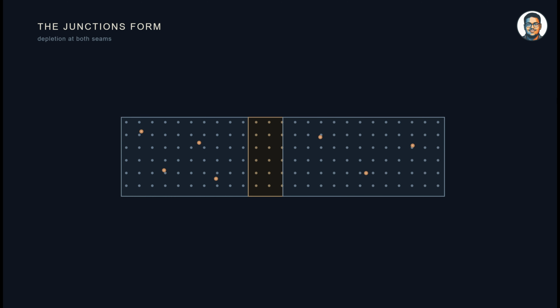Now, immediately after manufacturing, the electrons rearrange themselves such that at the emitter base junction, the emitter end gets positively charged and the base end gets negatively charged by the free electrons that flow from the phosphorus in the n-type emitter to the holes due to the boron in the p-type base. A similar scenario happens at the base collector junction, both due to diffusion driven by random thermal motion.